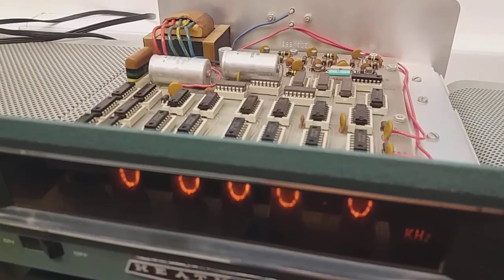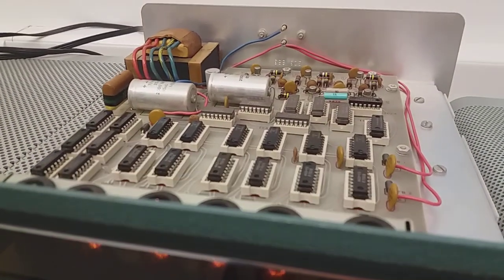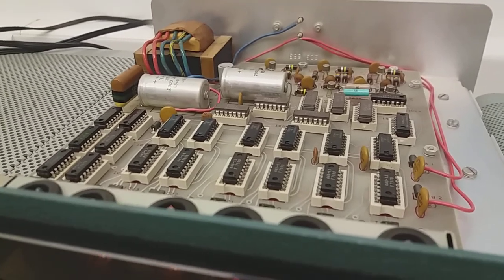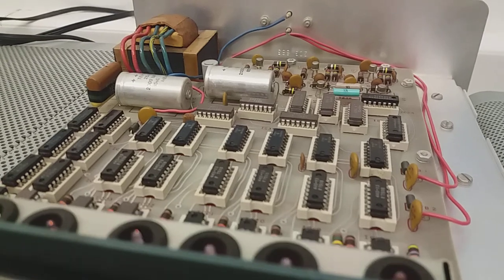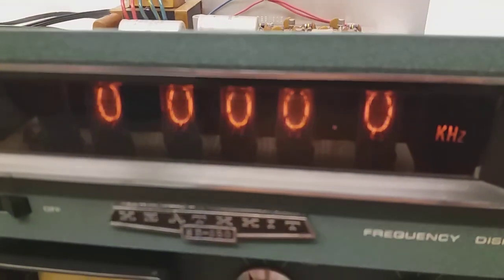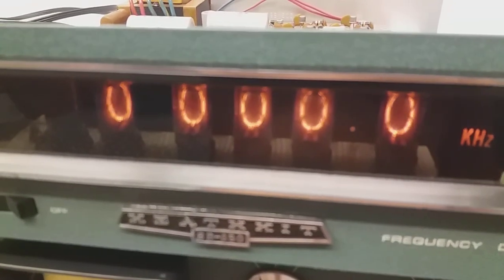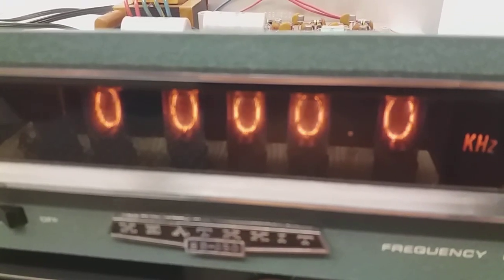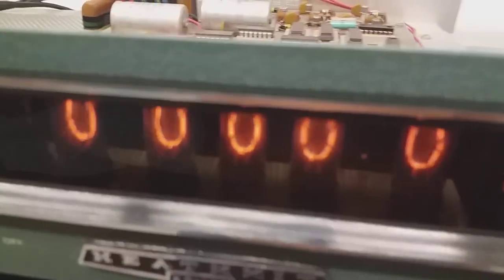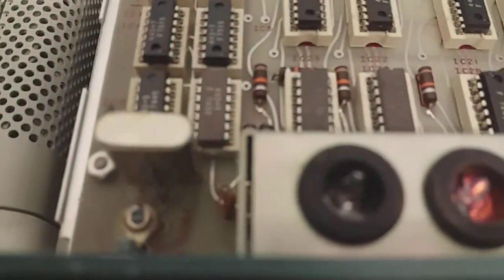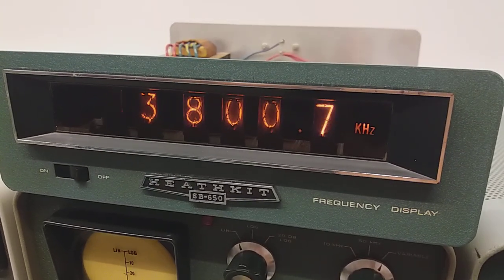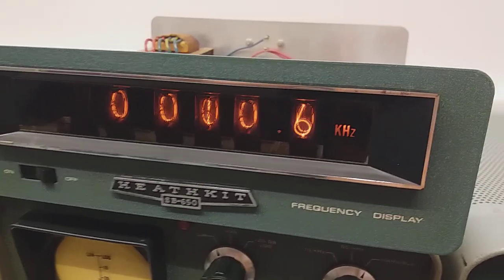So the things I've tried is to connect the input instead of the HFO to the VFO or to the BFO, and none of them worked. The frequency was a little bit lower than 0, but I could not set it to the right frequency. So at minimum capacitance I could set it even below 0, and at the maximum capacitance it never reached 0. So these two inputs go the other way around. So we're going to use the HFO anyway, but the maximum we can get is 500 Hertz here. Okay, that's the maximum we can get.